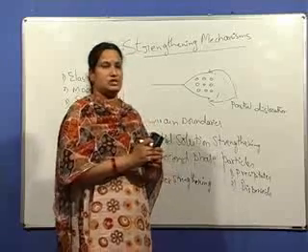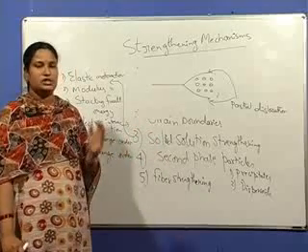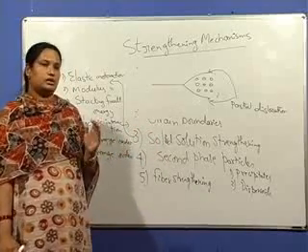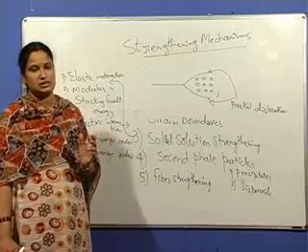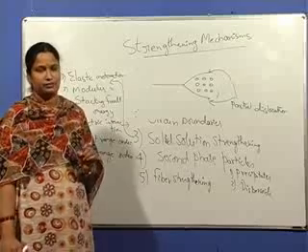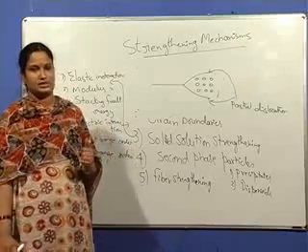Because of this short range order or clustering, for the dislocation to move, it requires more energy. Why? Because it disturbs the local ordering. Thereby, the strength of the material will increase.